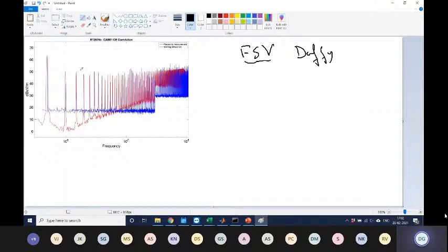In this particular case, what I've seen people typically do is compare the first few harmonics, the first 5 harmonics, for exact values, and then the envelope of the rest. So it's still not numeric. FSV is a completely numeric method. In fact, I met Alistair, and he was saying that in his PhD he faced the problem of how to represent the accuracy of his results, and then he came up with this technique called FSV. It is an interesting technique, and we did look into it. But in general, in the industry, they don't really do FSV today. They look at more commonplace things like the peaks at the harmonics and the envelope of the rest.